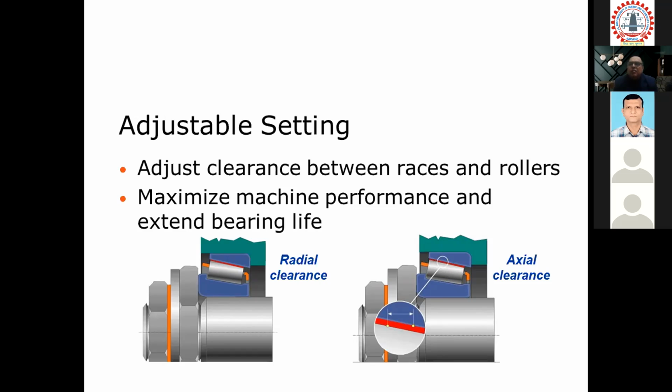So then your second question was on material. The bearings typically are a very hard material between 58 to 64 Rockwell C. But we also require high ductility, high ductile strength and high tensile strength.